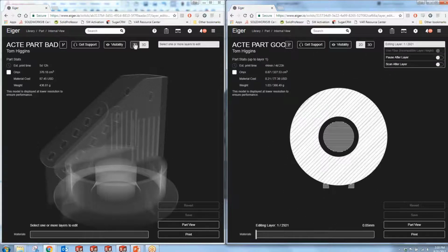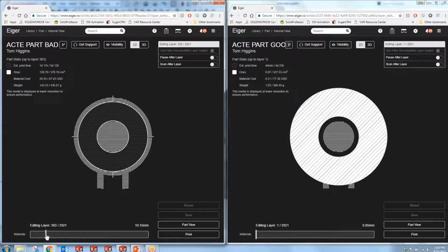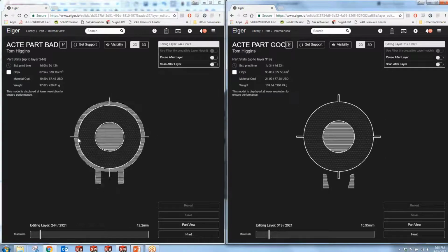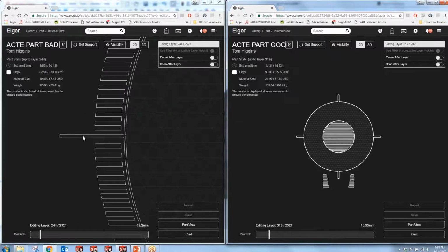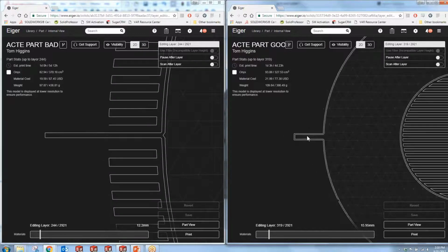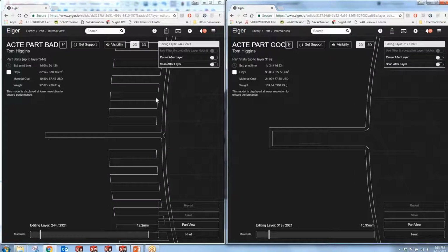Then we'll go to the 2D. So this will show thin walls, the dangers of having too-thin walls. Here, when those thin gussets would be laid, they only get 2 passes. Now, if the passes are close enough, they will fuse together, but you'll have a very flimsy, easily breakable gusset.